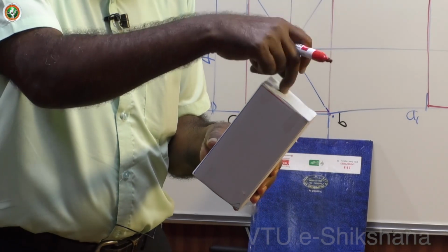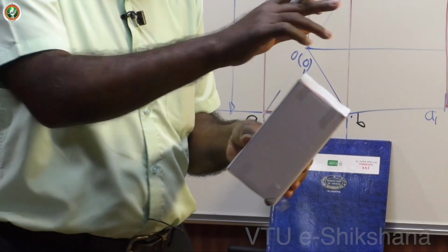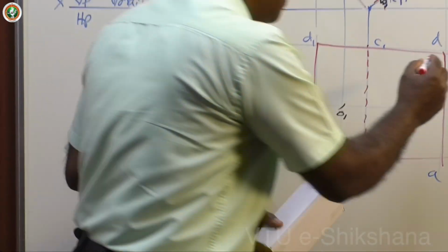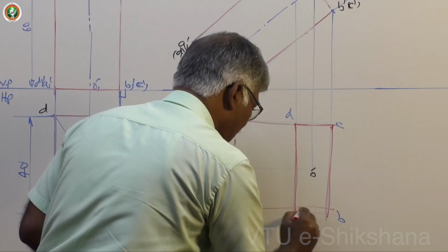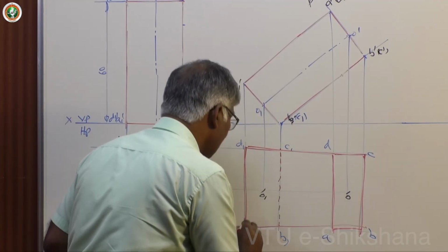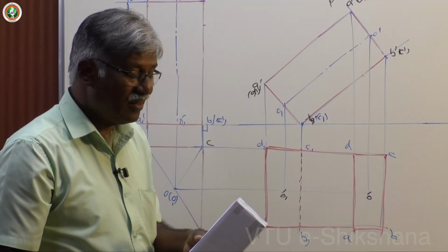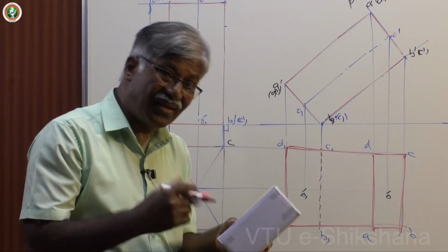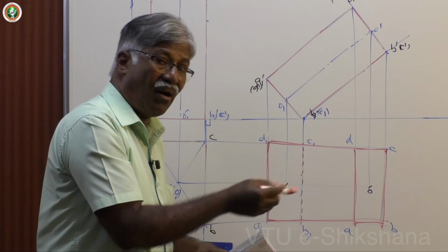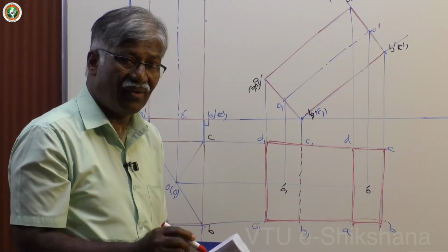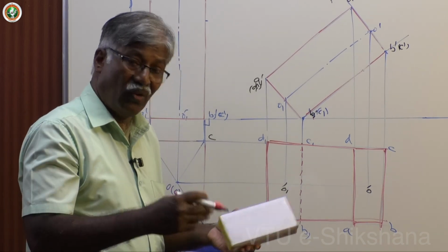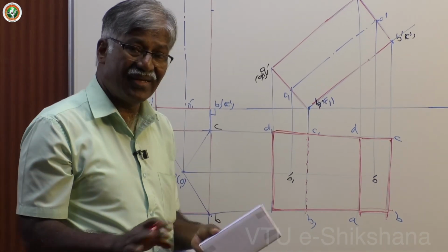Forget the latter surface, key surface 1. You can see only the top key surface. So, dark that. That is the only criteria you need to complete this figure. Dark the visible key surface. First, I will repeat this. Dark visible key surface. Then, keep all boundary lines dark. Okay. That's all. Then, invisible key surface edges other than boundary line. See, invisible key surface is A, B, A1, B1, C1, D1. Already 3 lines are covered by the boundary line. Only 1 line left out. Yes, that is dotted. Fine. Now, no in between lines. That's all. That ends the job.